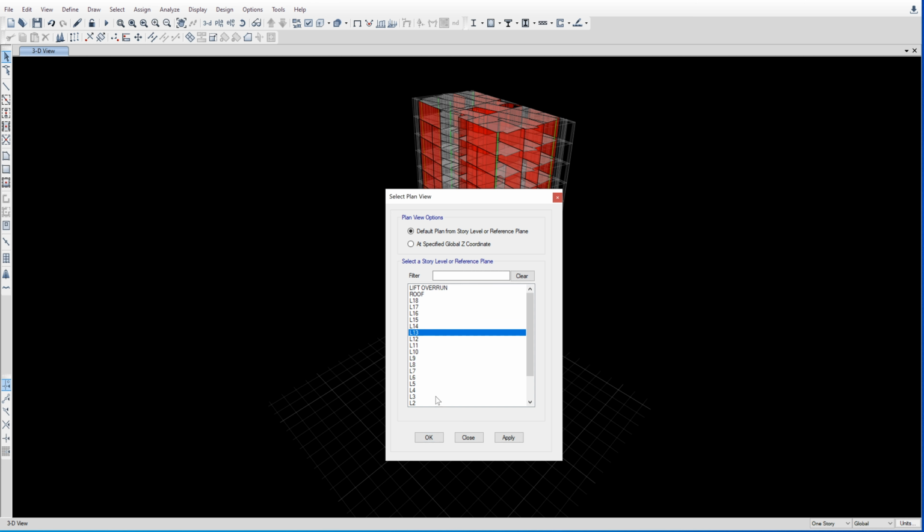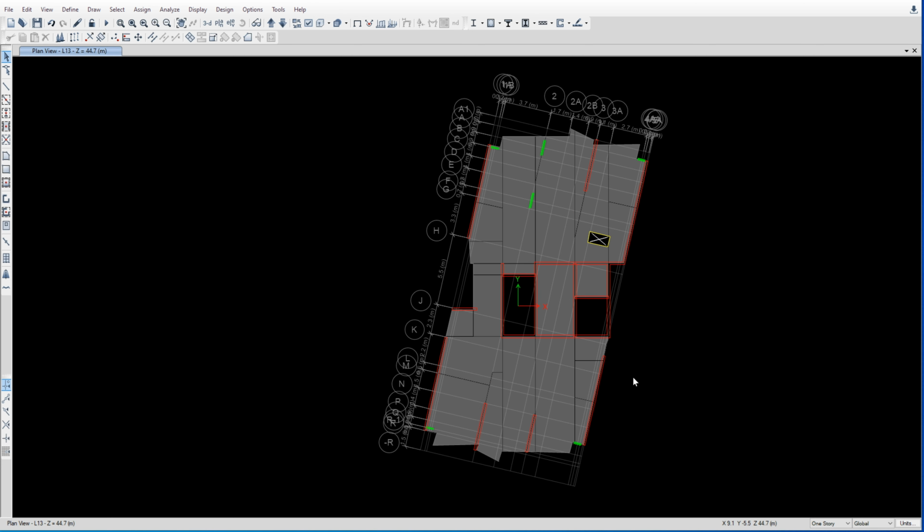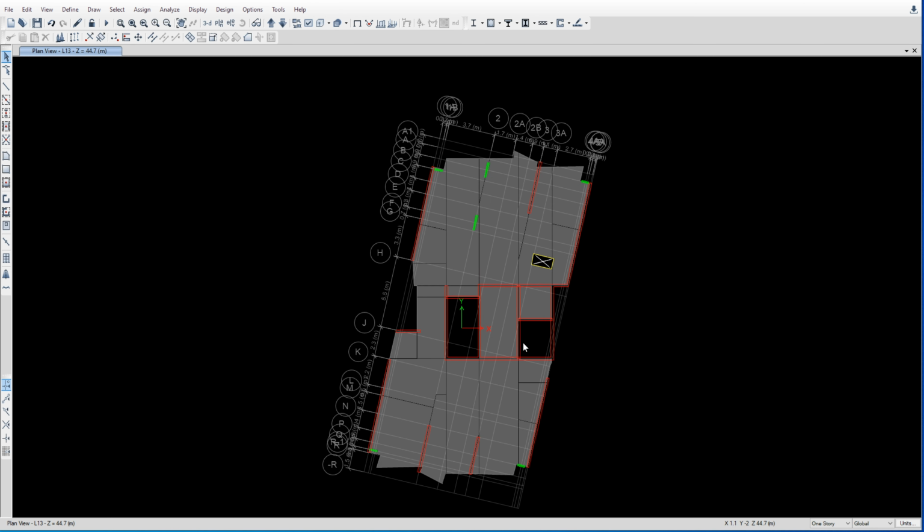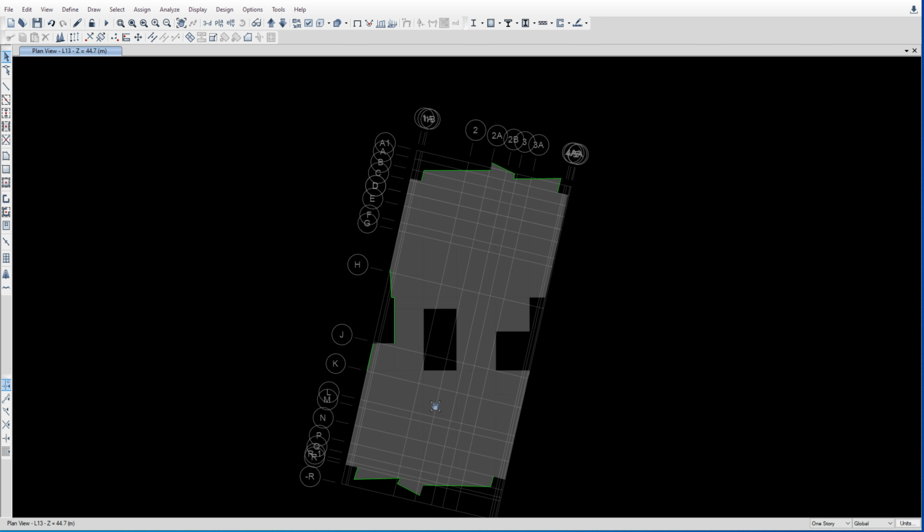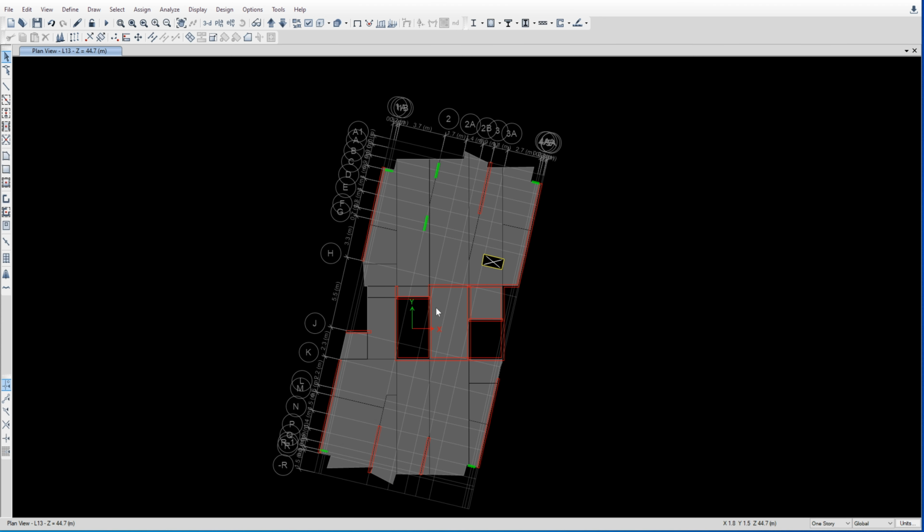the plans, we can see that the core was actually not 90 degrees with the building, and the building is not directly oriented to the north direction, and it's actually offset at an angle of about 13 degrees from the north direction. So that complicated it a little bit, and it becomes handy when you have the grids for the core wall and you have the grids for the building separate.